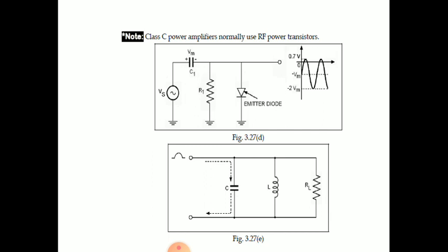The diode is from the transistor itself, because the base and emitter actually work as a diode. So if you replace that circuit and redraw it as a capacitor in series with the diode, and we are taking the output across the diode, it acts like a clamping circuit.